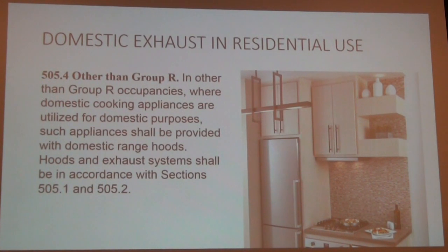Right. Suppressed? What about that? Not cooktop suppressed. Why is it so close to that wood building? What about that cooktop being so close to that wood? If it's metal, it's gotta be 24 inches away. Looks like there's some sort of flat exhaust system there. I'm talking about that sidewall. Sidewall. That's the refrigerator. Oh yeah, zero clearance. Yeah, that is a violation.